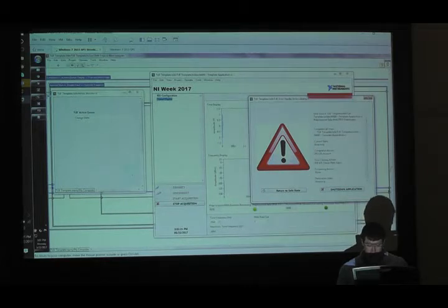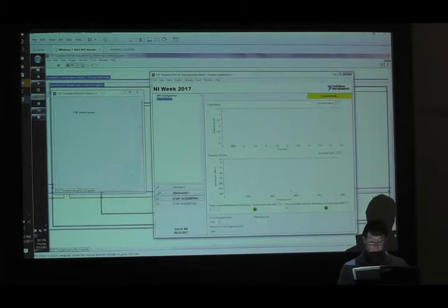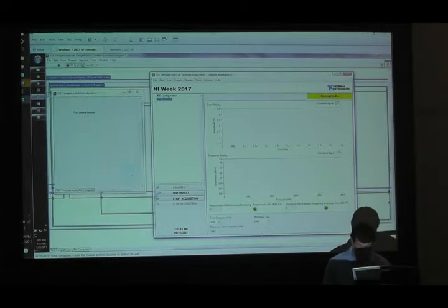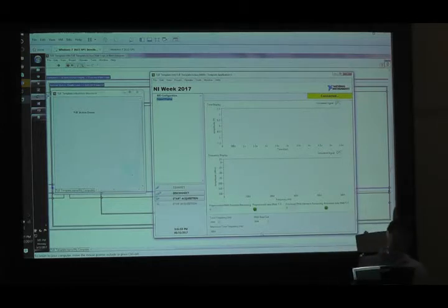And so I have the option right now of shutting down and returning to safe state. But because I know where I was at and what I was doing, I can still go back to safe state, and it will self-correct that behavior that was previously not there. The program does not automatically do that for you. You are going to have to write a little bit of code to figure out what it means to undo what I had done and get back to a safe mode of operation. And there may be moments where you have an error that is not recoverable and it's like, shut down. Goodbye, you're done.